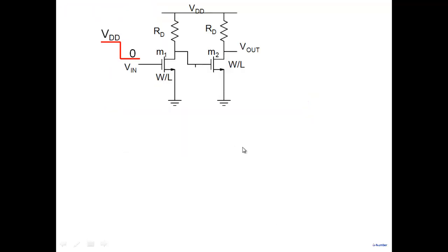All right, so how do we do that? Let's get to our inverter. This is our inverter, and note that you're never going to use any inverter or any gate isolated by itself. You will always have the inverter connected to something else. So as a load, we have considered another inverter connected to this one. We are interested in the propagation delay of this one right now, and the load of this one is another inverter.